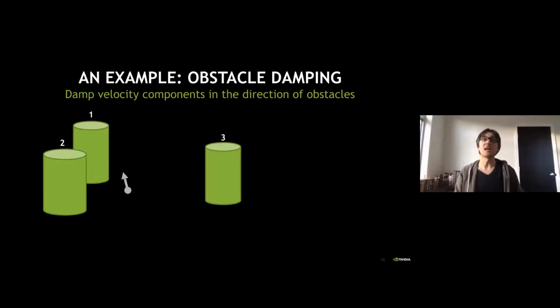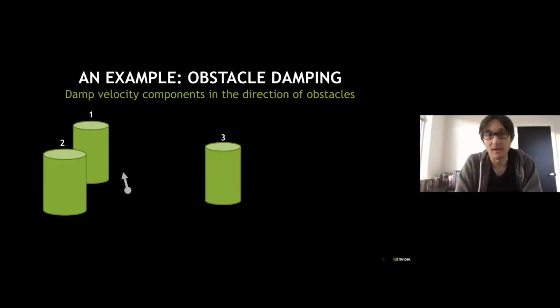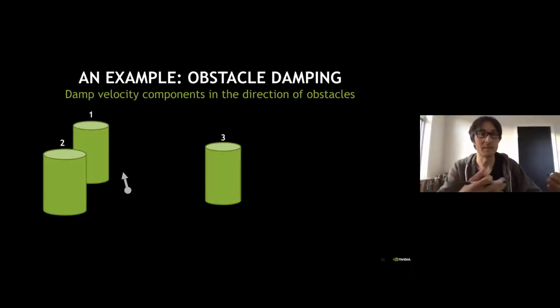And here's an example of what one of these RMPs might be able to express. If you think about obstacle avoidance, there are a lot of potential field methods that might push away from obstacles, or optimal control methods and stuff like that. But one intuitive description of obstacle avoidance might be: we have a position and velocity and a series of obstacles around us.